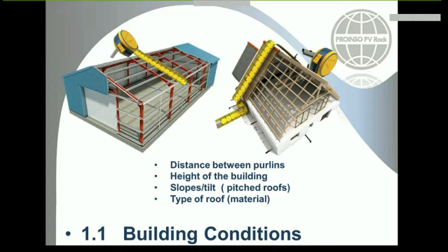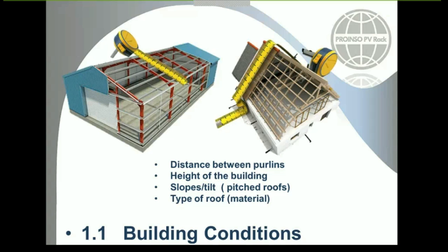The height that we take into account for our kits is 10 meters high. For all heights less than this, our structure has been designed for more, so there are no troubles on the loads that they have to support. But the more height you have, the more wind loads you have to support.